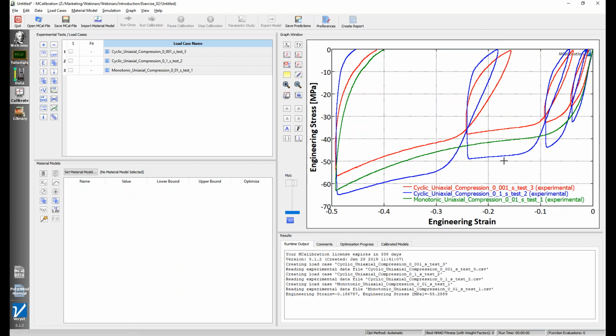No, sorry, a polypropylene material. So this is compressive data. So we go up to fairly large strain in compression. We go to almost 50%. You'd also see that we have some cyclic data here. So the green one here is a monotonic all the way up to 50%. We're just below that. But the other 2 are cyclic.